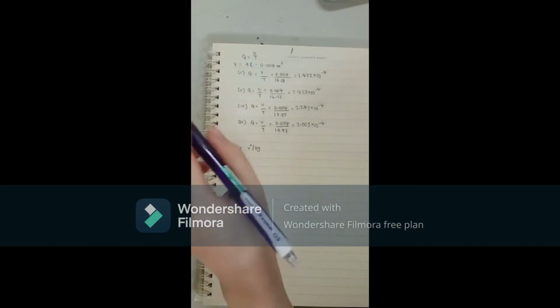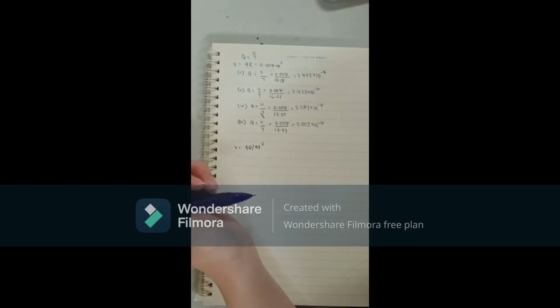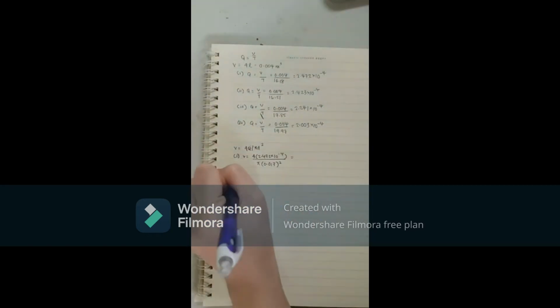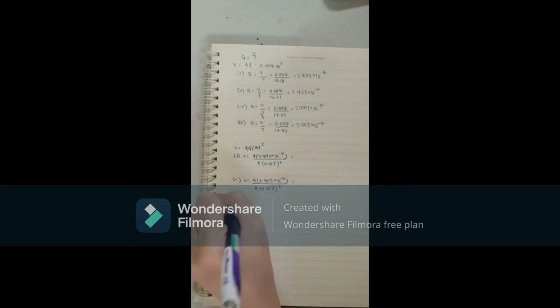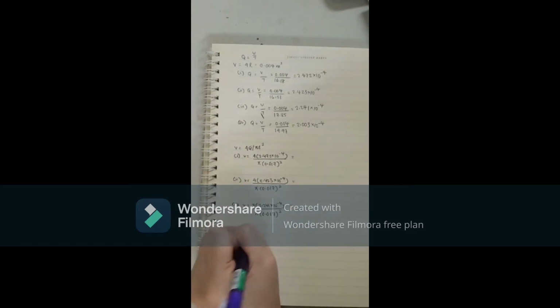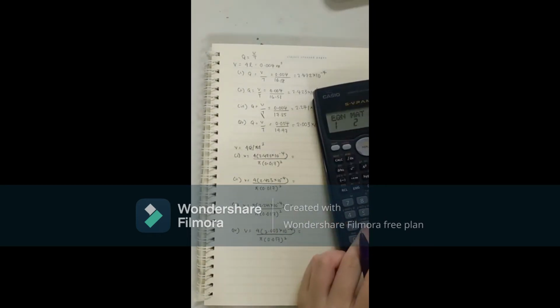So this is the video of me calculating the volume flow rate, where I get to change the unit. The volume given in the video is in liters, so I change it to meter cubed, where 4 liters equals 0.004 meter cubed, and I use the formula for volume flow rate, which is Q equals V over T.